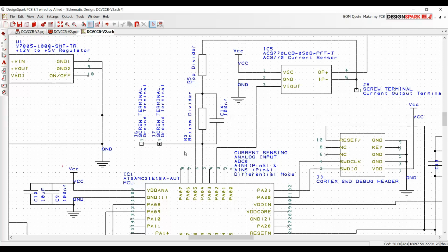Or B, should I tie the negative terminal of the motorbike's power to the ground of this board, and therefore I can do a single-ended reading on ADC1, keeping it separate from ADC0? Or should I change to the sigma delta version on these two unused input pins?